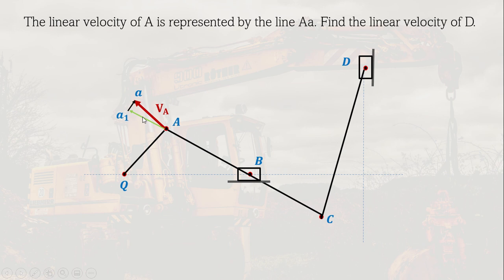So we resolve that component into the points that we'd like to get its velocity. So we resolved it because this is the line joining A, B, and C. That's why we draw the same. We measure AA1 and then we draw it here. And then the direction should also be the same. And since we know that the direction of B is in this direction or that direction, we're just going to draw an arrow that will connect it.